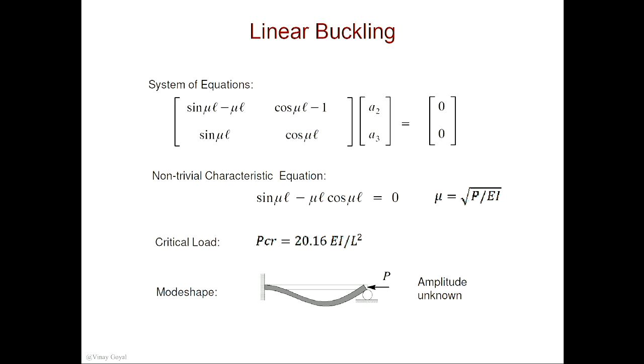And in fact, if I were to perform a test on that ruler with these boundary conditions, with that length, with that E modulus, with the moment of inertia of the cross-section, I will get a critical load in the test environment that will be similar to this. It will not be exactly that, but it will be quite close to that. Okay? So it's one of the few areas in structures where buckling only depends on the geometry and material properties.